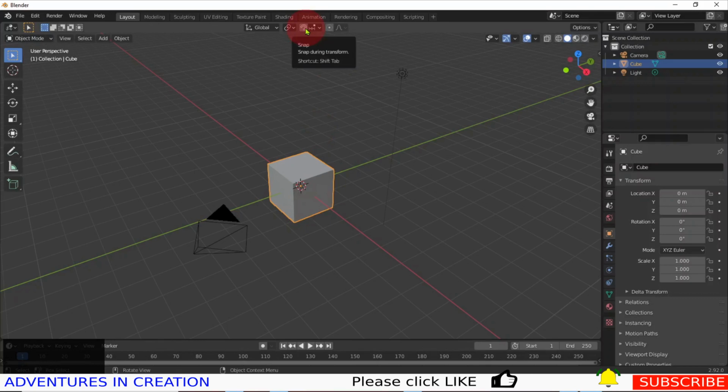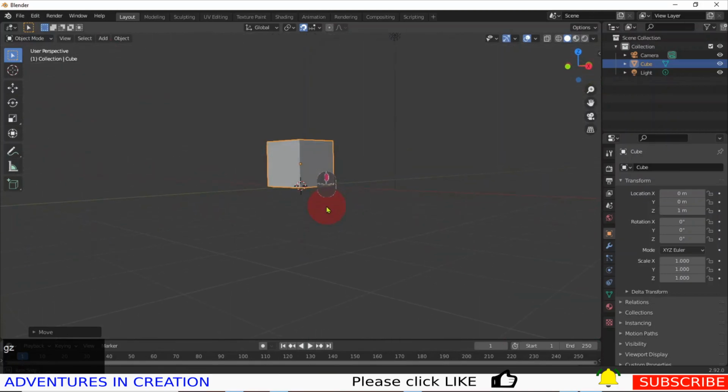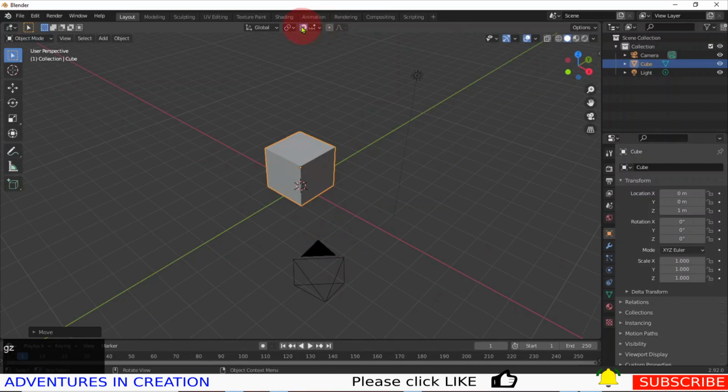So I'm going to turn on this little magnet up here. This does snapping. You can play with this, but I'm just going to turn it on for now. And I'm going to do a G to grab this cube and a Z to move it up. And I'm going to bring it back down, just drop it there. And now if you look, it's sitting on that surface. So that's all I wanted to do. I'm going to turn my magnet off for now.